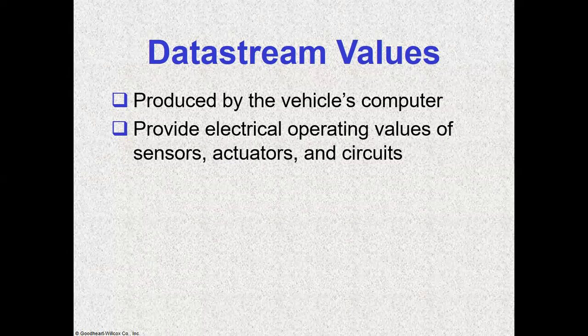So the readings change from thousands of psi to megapascals on these readings, and those are the pressures. Just imagine the power washer you use to wash a car. Most of those go up to like 17,000 psi, and you have an injector in your vehicle spraying at 36,000 psi. So this is why we don't normally use regular fuel pressure testers to test these things.